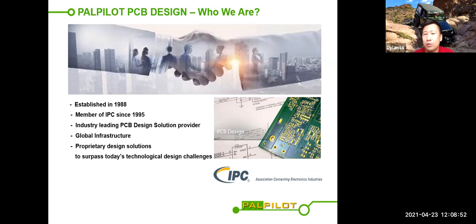But of course, when you get into a more complex or comprehensive type of design, you sometimes have to violate a little bit of the IPC rules to be able to finish that layout. But PCB fabrication and assembly also have to adapt to IPC rules and specs. And IPC also has a different book for the specification for qualification. It would be really good to understand that as well when you receive the PCB, to see if it passes the quality assurance based on IPC's expectation.